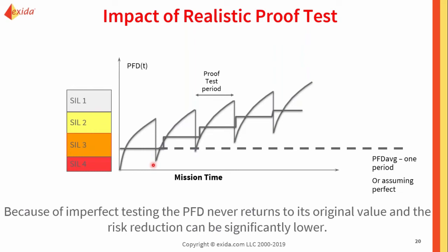However, we know that each proof test, you're not at 100%, and your PFD average is going to creep up each proof test. When you look at the PFD average for the mission time of the SIF, this one being a 5-year, we're actually up here instead of the PFD average for that first. This would also show you the difference of assuming that perfect proof test, or 100%, compared to that more realistic, or 80 or 70 or whatever it is calculated in this example.